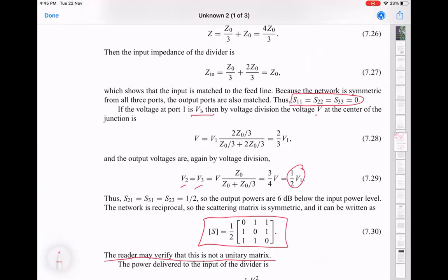calculation because the methods we used are identical to what we would have used if this was a low frequency circuit as well. I can always convert from voltage to power because there was no wave aspect of it really used. In practice, whether you can make 3 resistors like that, which are only resistors without any capacitance or inductance at all the frequencies of interest, is what will determine its true performance in the microwave frequency range.